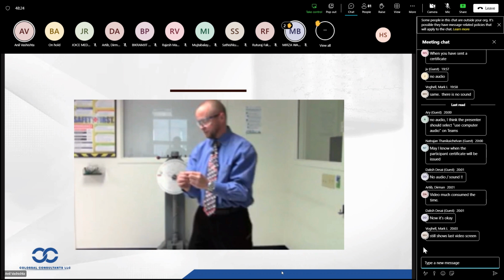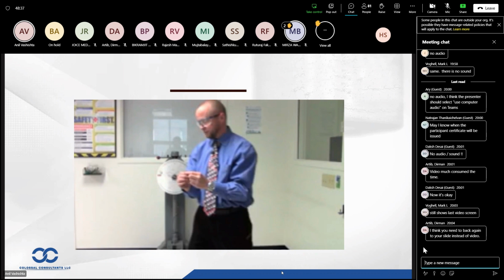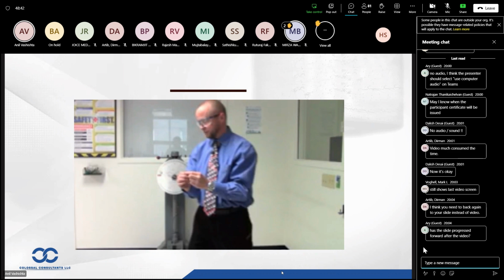XRD is another method. X-ray diffraction is a non-destructive method to analyze the structure of crystalline materials. It is used to identify the crystalline phases present in a material and thereby reveal chemical composition. OES is used for chemical analysis of metallic samples. A small portion of the sample is taken and analyzed using OES, optical emission spectroscopy.